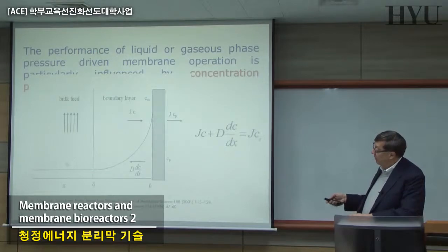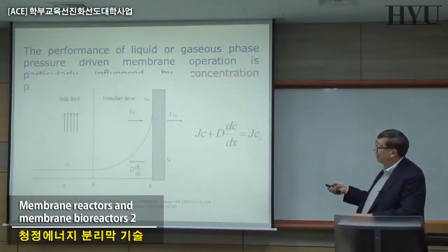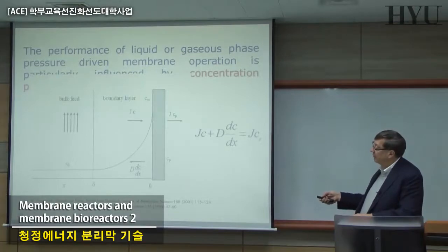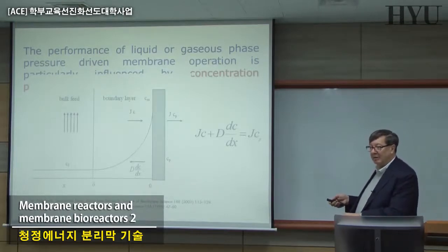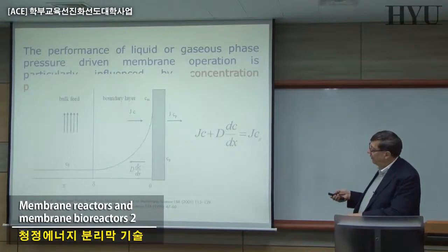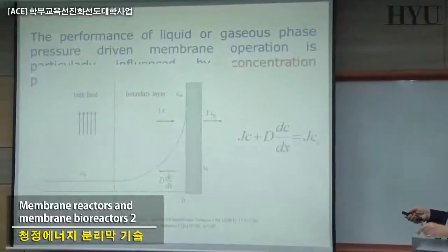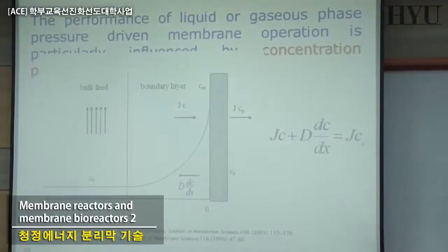First of all, just to remember that when you are talking about concentration polarization, this P stands for polarization, it is nothing more than this: this is our membrane, and normally you have a homogeneous solution on the feed side, and that means the concentration is the same in any small element that you are trying to characterize. But as soon as you start to permeate something, the situation is changing. What is happening here is that the membrane that we have here is semi-permeable, so something is going through, the species that are permeable in the membrane.